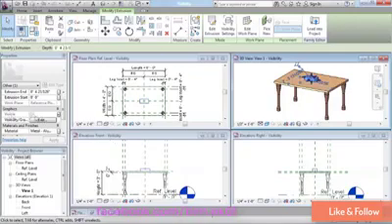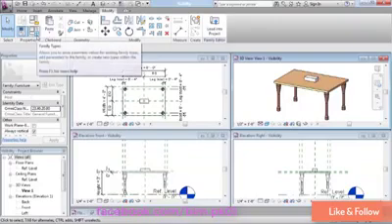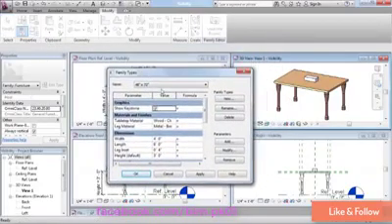This will gray out the visible parameter. It'll put an equal sign on the button to let us know that that's now being controlled parametrically. And otherwise, there's not really any other clues that you'll have on screen that this is being controlled parametrically. Now let's do one other thing. Let's return to Family Types, and let's add a new type to our family that uses the keystone setting.